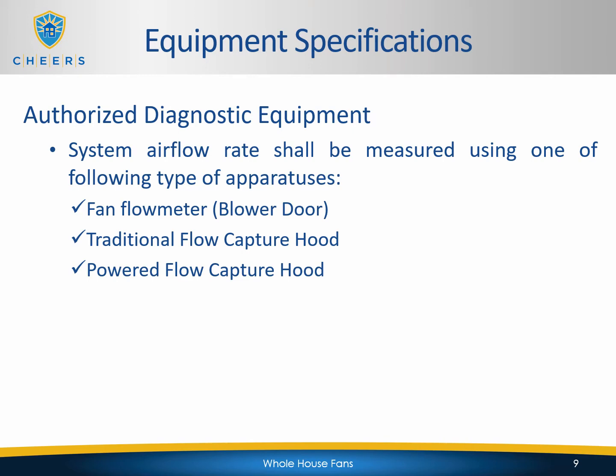Authorized diagnostic equipment. System airflow rate shall be measured using one of the following types of apparatuses. You can either use a fan flow meter, which is more commonly referred to as the blower door, a traditional flow capture hood, or a powered flow capture hood.